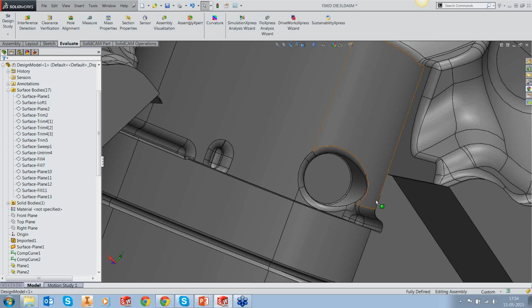Of course, you can say I can put a radius, but still a radius is a speed breaker for me. Why do I need to get these things when I can just close them off and handle them later, targeting only those areas? Sometimes it's more effective to just do an EDM on this than to do milling, because they are deep. If you don't have a 5-axis machine, then it doesn't make sense to go into this area with a small tool.